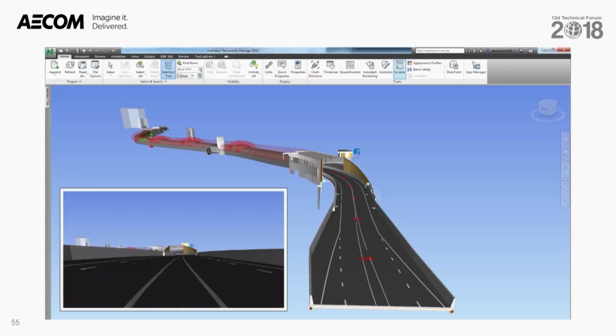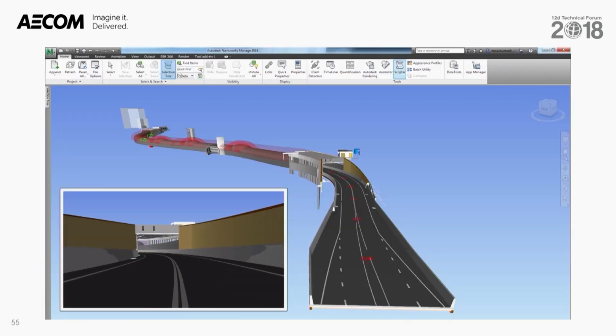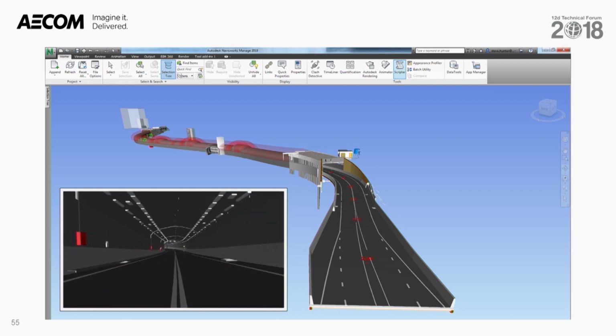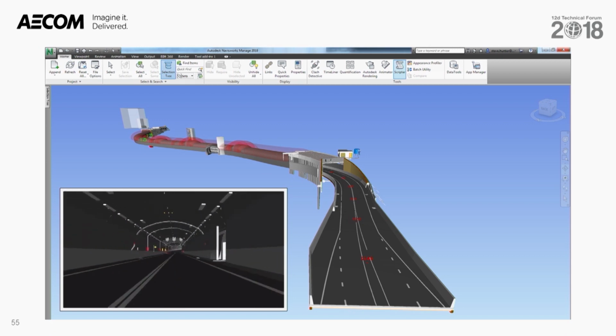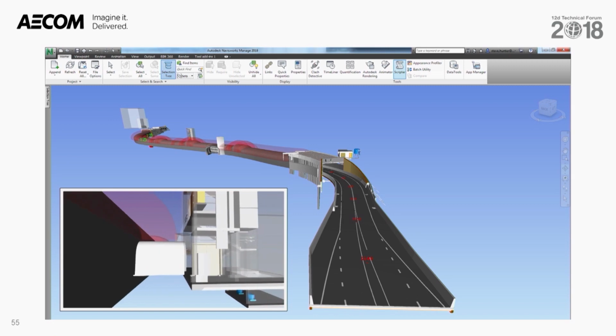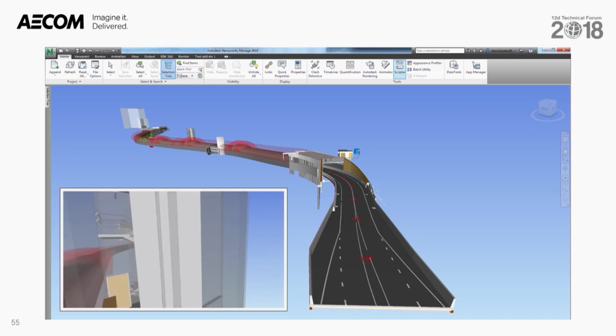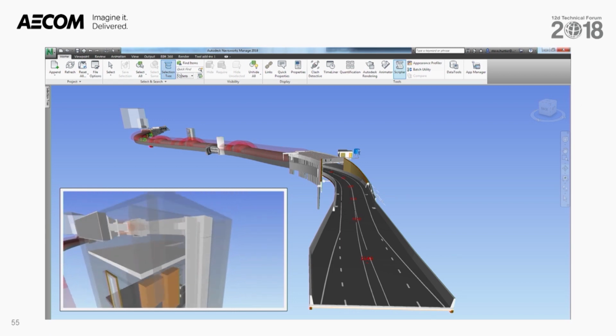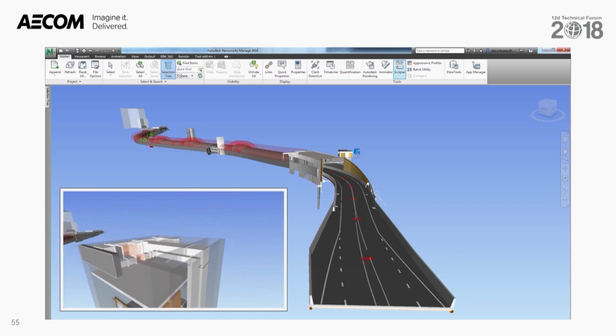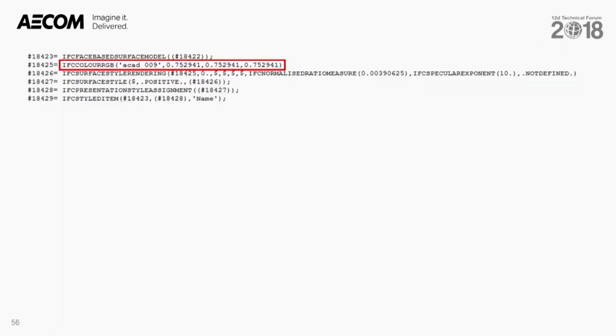Our common data environment for our federated engineering model is inside Navisworks, where we also send data from other sources such as Revit, and formal clash detection reports and other BIM work is done by another team to free up our 12D designers to do design work. And our most common format of export from 12D is IFC, particularly for objects such as pavements, barrier systems, etc. But there is an annoying deficiency in Navisworks that makes this process frustrating and inefficient.